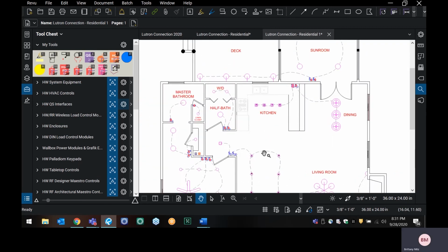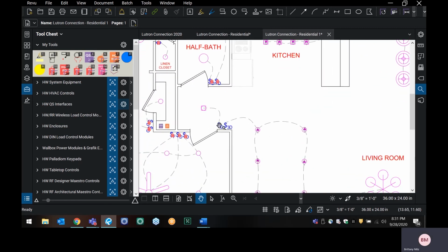And now, for example, here we have $D. So that's where we might want to stamp a Pro dimmer. So again, I can go over here, hover over where's my Pro dimmer and pull that right into our floor plan. So I just selected it. I come on over here, right on top of $D, click, and then I hit escape.